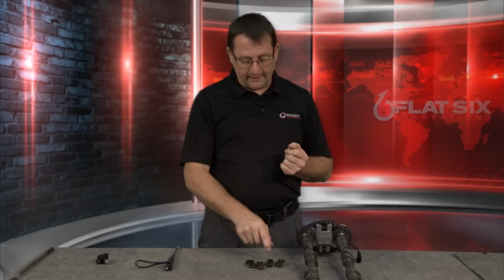It was a one-owner car. But the problem with that car is it more than likely sat around and probably had maybe 3 oil changes at most in the amount of time that it was in service. So that nasty old corrosion-filled oil with all this nasty stuff in it, fuel intrusion, everything else, condensation, had sat there and it had worked on this factory material. I told him, we cannot do the IMS solution installation. Your engine is disqualified. He says, what in the hell are you talking about?